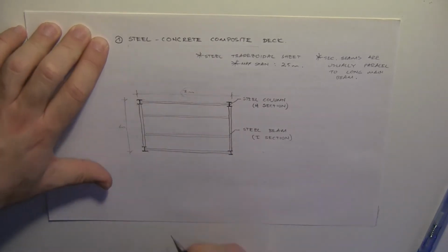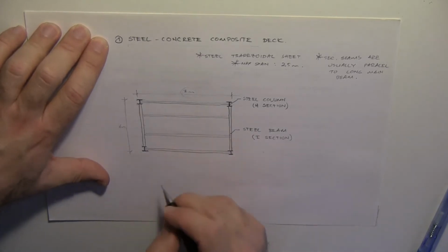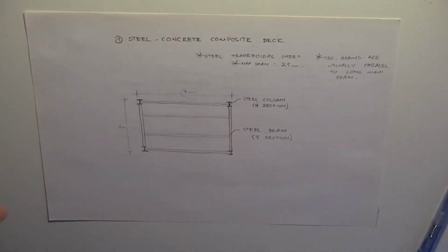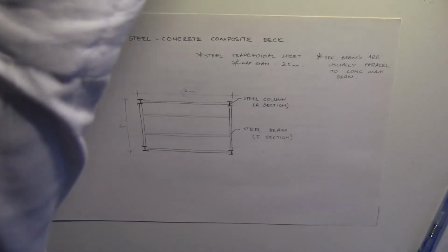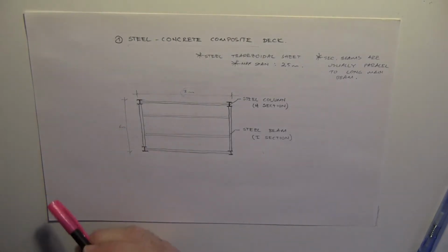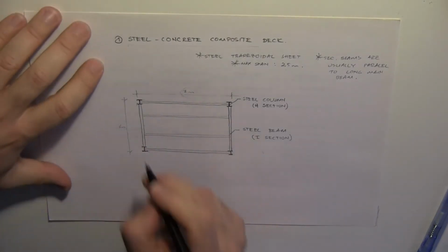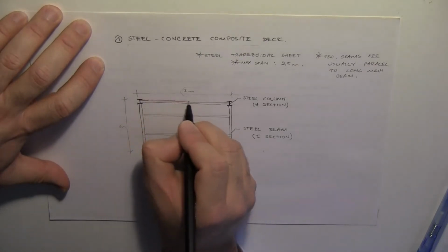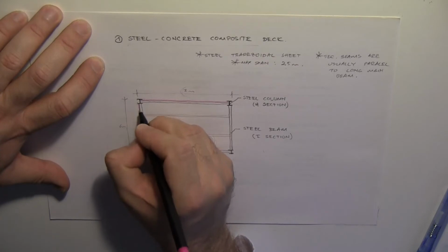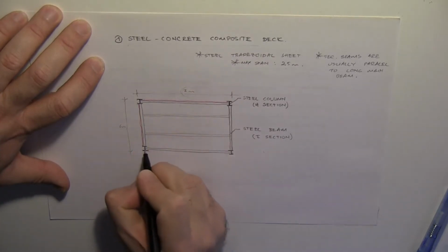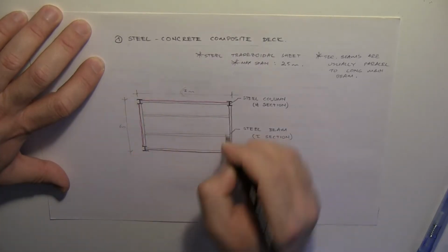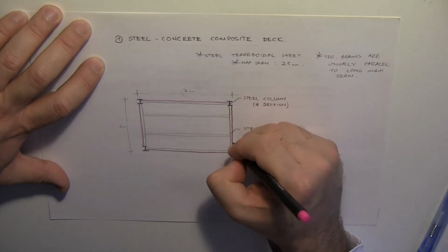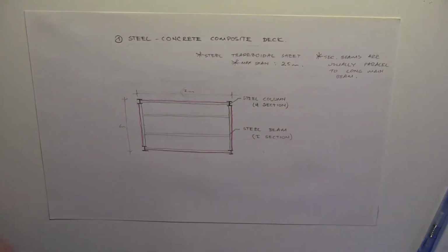Okay, and then what will I do? I am going to do a couple of things. Now maybe colors will be alright. Firstly, I need to surround my main beams with an L profile, because after I place the steel trapezoidal sheets in their places, I'm going to cast concrete and I don't want that concrete to flow outside.